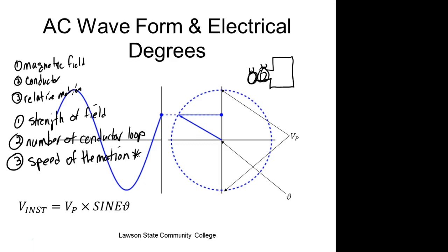How would you know if you've got a problem with your alternator? Well, when it cranks up, if it cranks, your alternator should put out over 14 volts. It's a 12-volt battery, but it's a lead-acid battery, so to charge those things, we put more voltage on and force current back through the battery. So a regulator should regulate it. Your battery, if you let it set overnight, should measure pretty close to 12 volts. If you go out there right now and it's measuring like 11 volts, that means either the battery's bad or it's not charged.